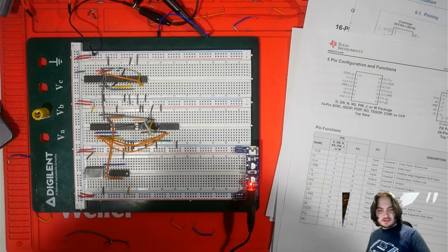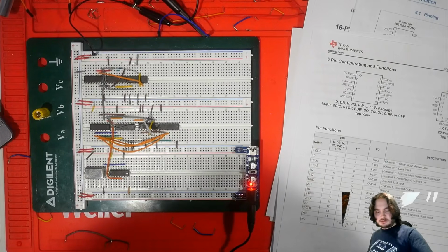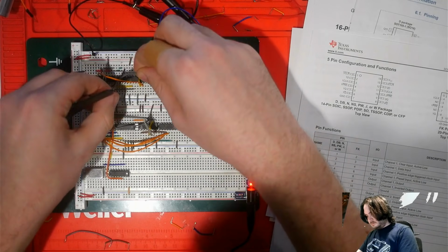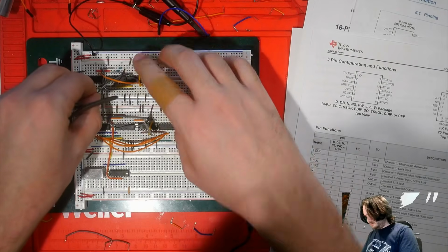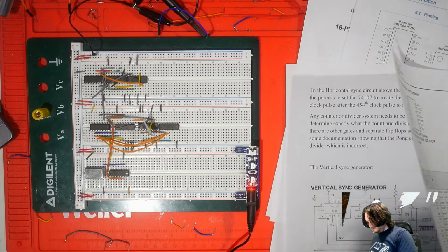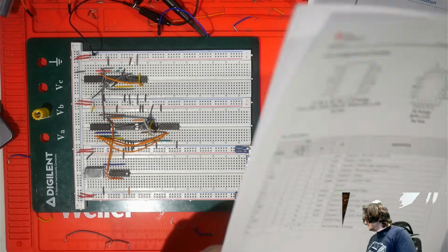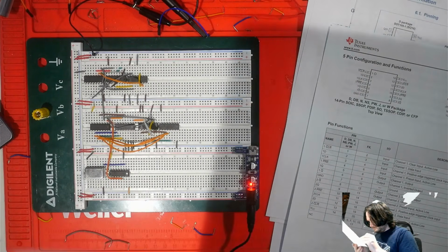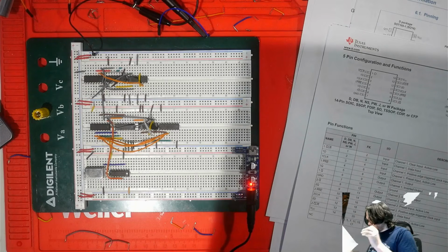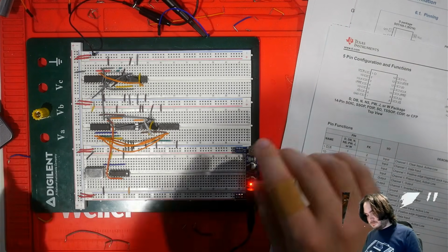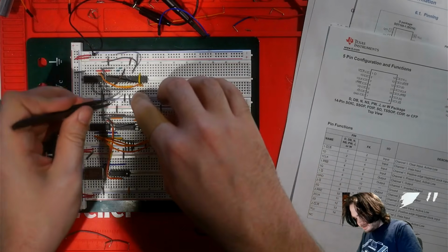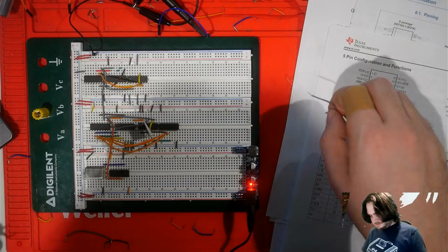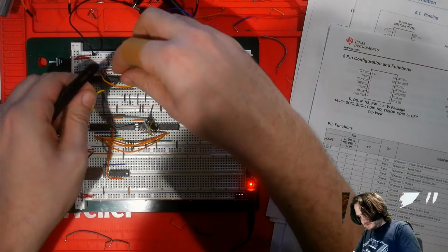And then 16V will be what clears it. Is that clear, or do I need to invert that? I need to invert that. So we can use one more NAND from this side as an inverter.